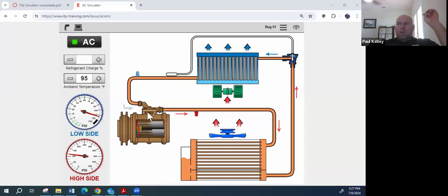You could also, if you were picking up on what we were doing when we did that diagnosis together, feel and test to see if that relay's clicking. If the relay's clicking, that means the control side of the circuit is working. If the relay is not clicking, that means something is not activating the relay. So you could go in two directions. If the relay is clicking, then you're really going to have to check for voltage at the compressor. Totally agree. If the relay doesn't click, however, then you may have to start looking into other things, right?